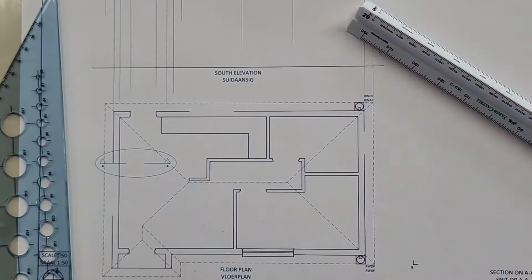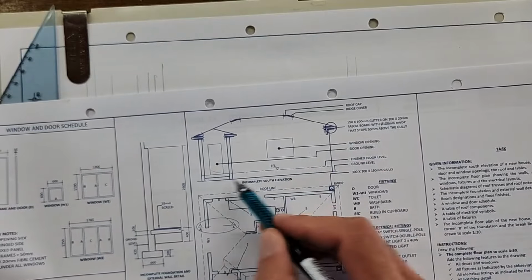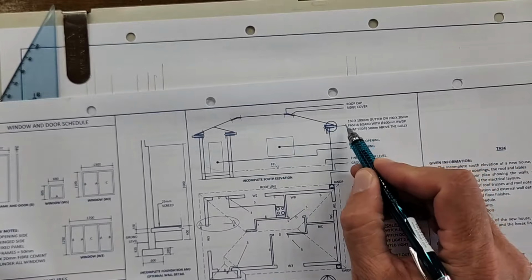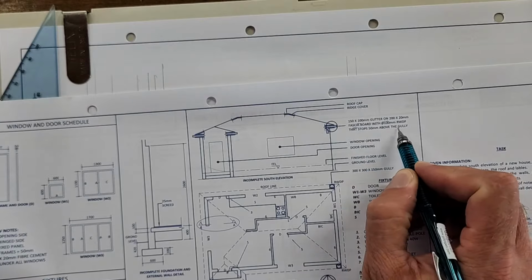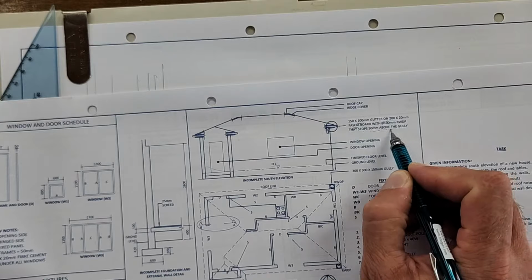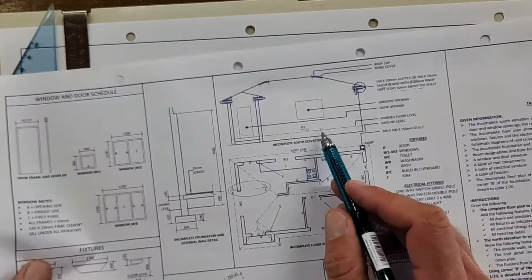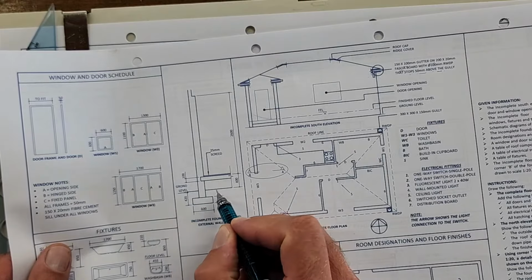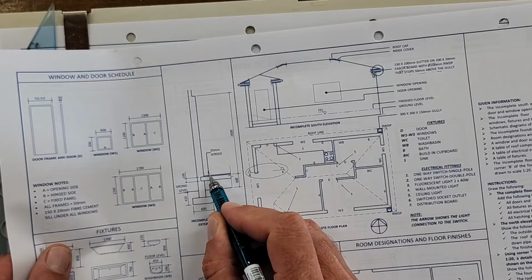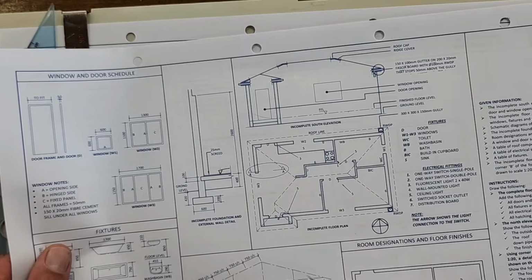Okay, well now we can almost go home because half of this drawing is done. We're going to now be using the information that's given here to complete this view. We're going to pay attention to the fascia, the gutter, the fascia boards, the stops, the 50 mm above the gully. So that's the stop of that water down pipe. Height of the finished floor level, we're going to have to determine that here. If you look at the natural ground level, then there's a 400 plus that 25 to get to the top of the finished floor level. So just pay attention to that.